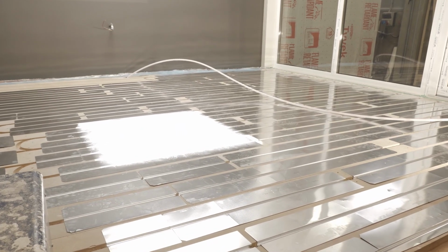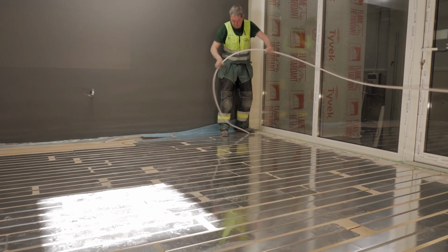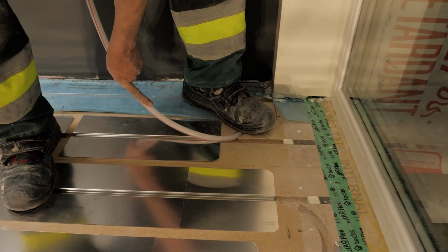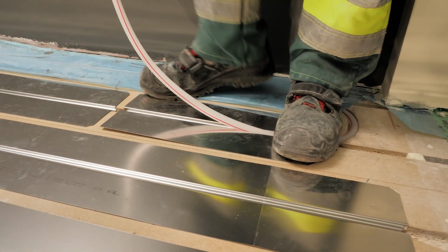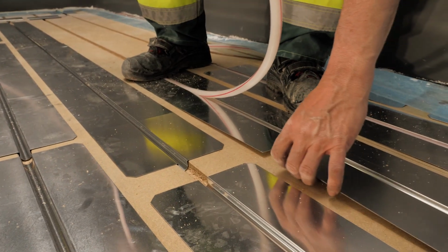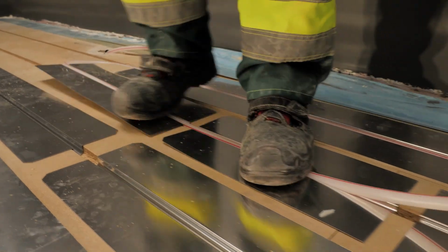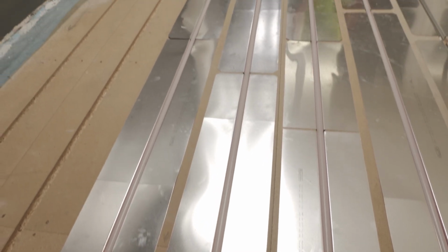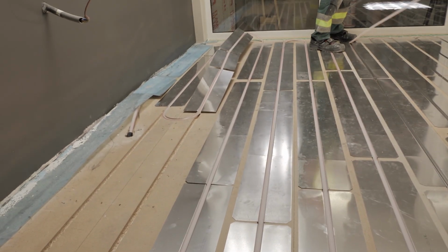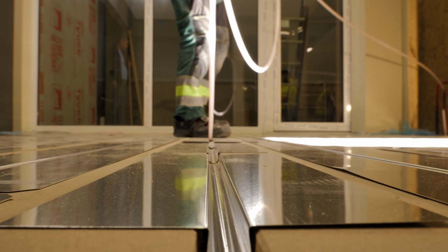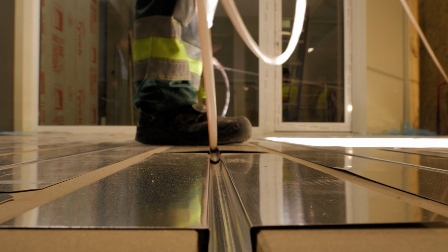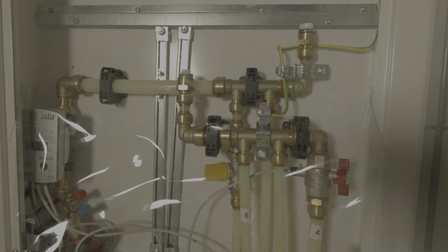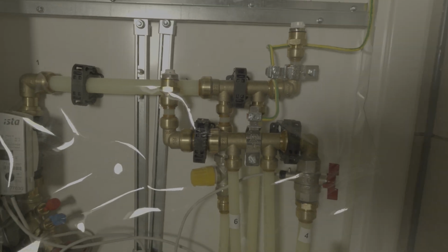Sometimes water-based underfloor heating is used to heat a building or different rooms. In this case, various solutions can be used to install the heating pipe on the floor element, such as grooved boards, where the pipes fit snugly. As well, aluminum sheets can be used in the grooves to help distribute heat evenly across the floor. If the underfloor water heating is used in bathrooms, then, just like with electric heating, the layout of the heating pipes should follow the design plans, keeping in mind the location of the floor drain and not be placed too close to the drain. The heating circuits are connected to a central collector cabinet, where the distribution and control of heating throughout the building is managed.